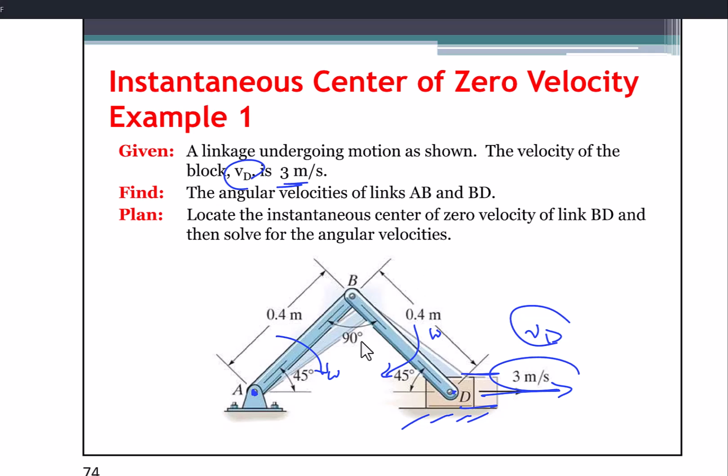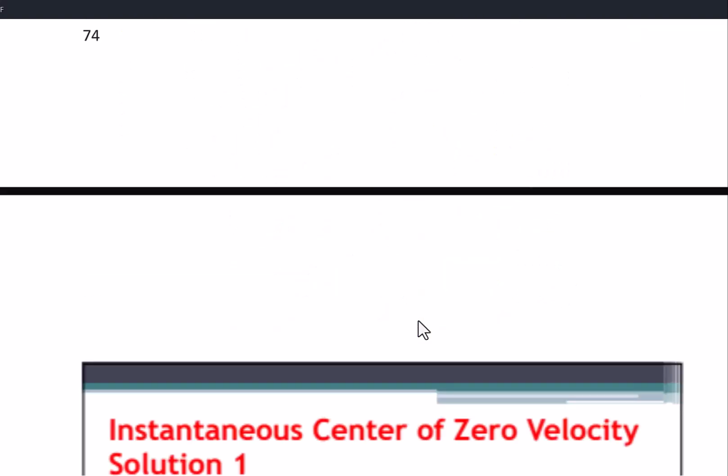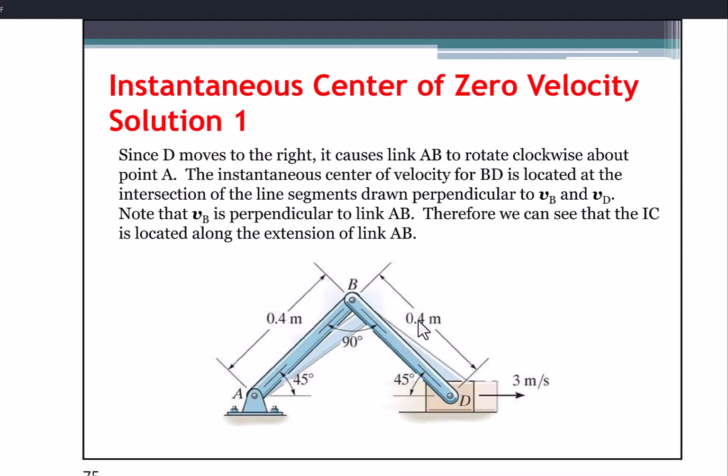You notice right away that this is constant, this is AB, we'll come to it, that this is fixed here, and this is pure rotation about this point. Here this has a given velocity. So this velocity is easy to relate to this guy using this R. But the problem is that this R is changing. But we don't care, because like we said before, it's relative to the instantaneous center of zero velocity. Let's look at how this can be solved.